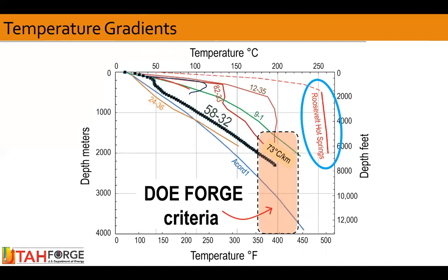Beneath the Utah Forge site, the temperature profile in 5832 is linear, increasing steadily with increasing depth at a little bit greater than 70 degrees C per kilometer. The maximum temperature is at the bottom of the hole, and it has a value of 199 degrees Celsius. Again, this even temperature gradient represents heat transfer by solid-state conduction.